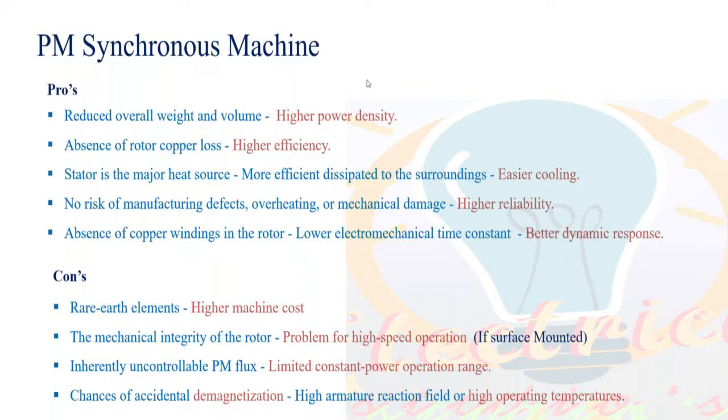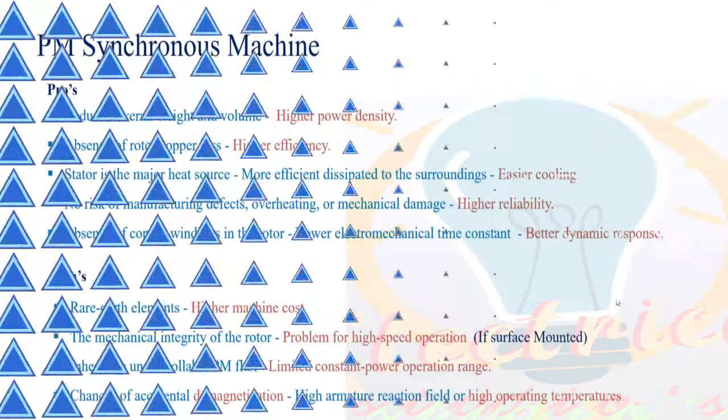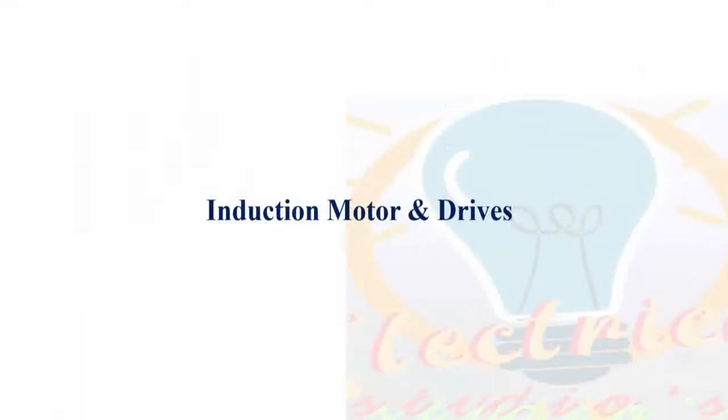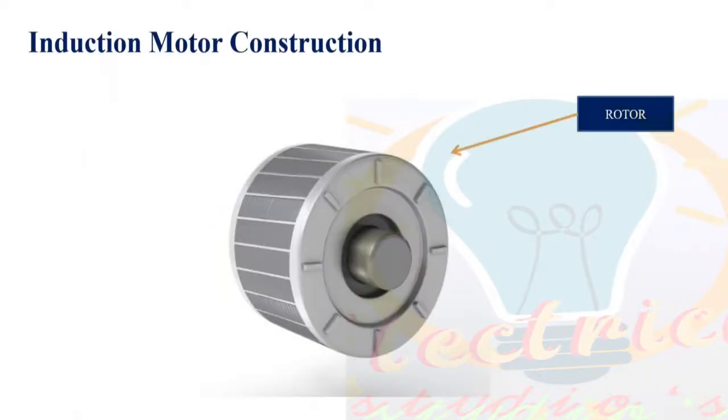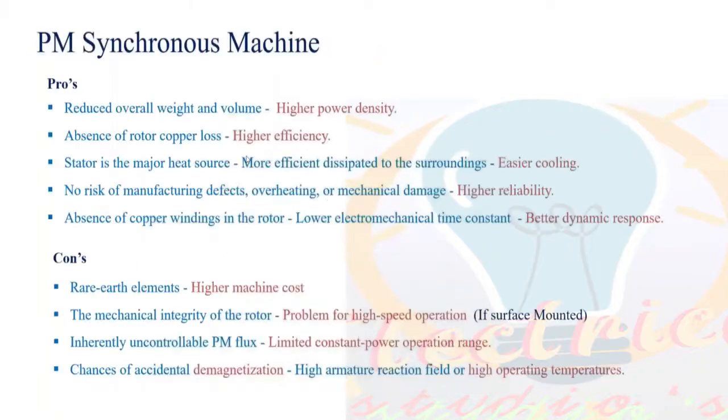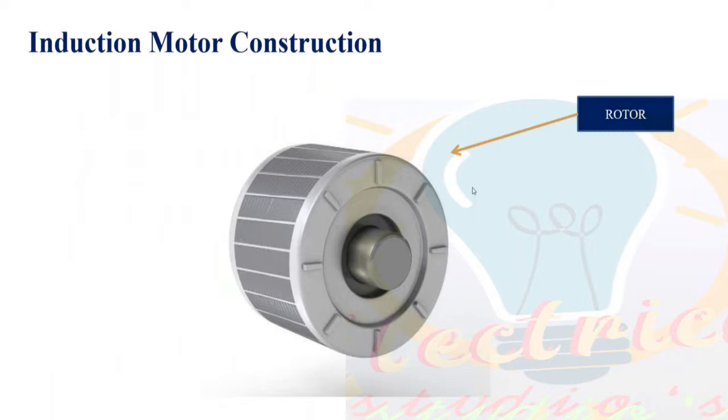So the PMSM motors are a very good candidate for high speed applications. In the passenger car segment and the high power segment, you can take the PMSM motor, but at the same time your price, everything will increase because the control is very sophisticated, and with more and more permanent magnets, the cost will also be more. And as I told you very clearly, the change is only happening on the rotor side. Similarly, when you look at the induction motor, the common thing is that the same PMSM stator can be used in an induction motor also.